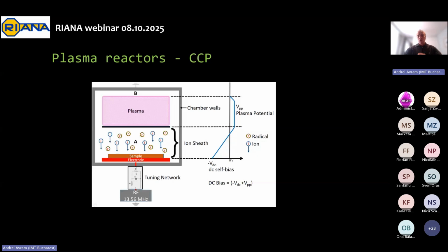Yeah, so the lower electrode is energized, and it's basically like, you know, one plating of a capacitor. Then you have the generated plasma that acts as the second plating of the capacitor. And usually, basically by the way that we apply power to the electrode and make the electrical connections, usually the lower electrode is negatively biased.